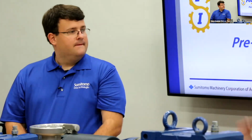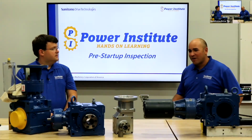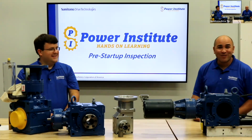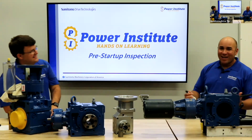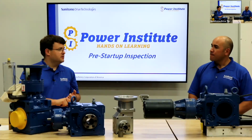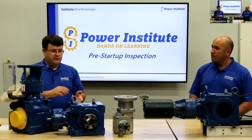And for other manufacturers, again, I keep asking this question because I know there are some people on that may not use Sumitomo. We'd love for you to use Sumitomo, but you may not, so we want to be cognizant of that. To make those changes, obviously consult with the manufacturer or their catalog to understand if you're going to do some mounting orientation changes. Yeah, the key thing there is just know where your fill and drain plugs are, where your breathers are, and your oil sight gauges are.